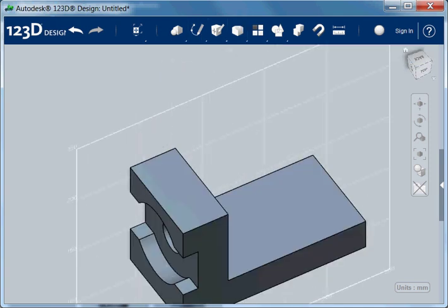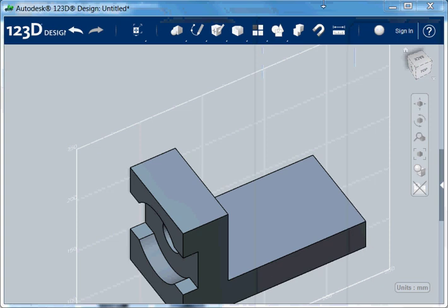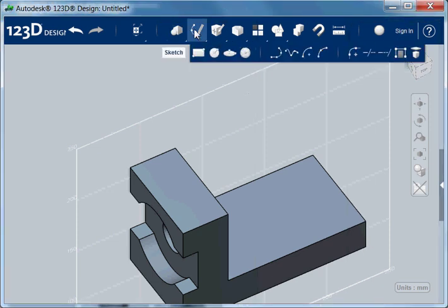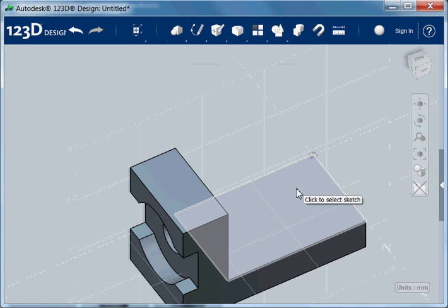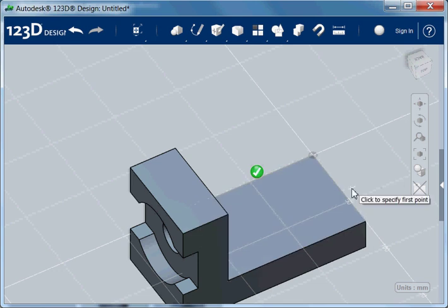And now, next part, we are going to make this cutout, which is 50 and a radius of 12. Polyline, and then I select this sketch. Two things you can do. You could make this by a square and a circle, and they work together, and it's all nice. But for learning purposes, I want to show you something else.